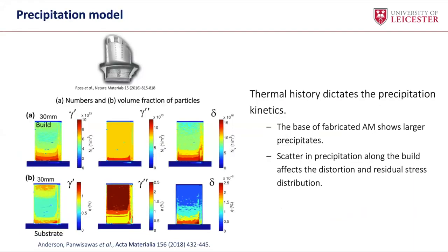Another thing that concerns metallurgists is the phase transformation, especially solid transformation. Precipitation is so important in governing your mechanical behavior. For example, in nickel-based superalloy or titanium alloy, a two-phase structure, you want to know the precipitation content or secondary phase content embedded in your final product, because this will determine whether or not it will fail during service. And because of the spatial signature of the thermal signature that I mentioned earlier, the distribution of this secondary phase is not homogeneous.